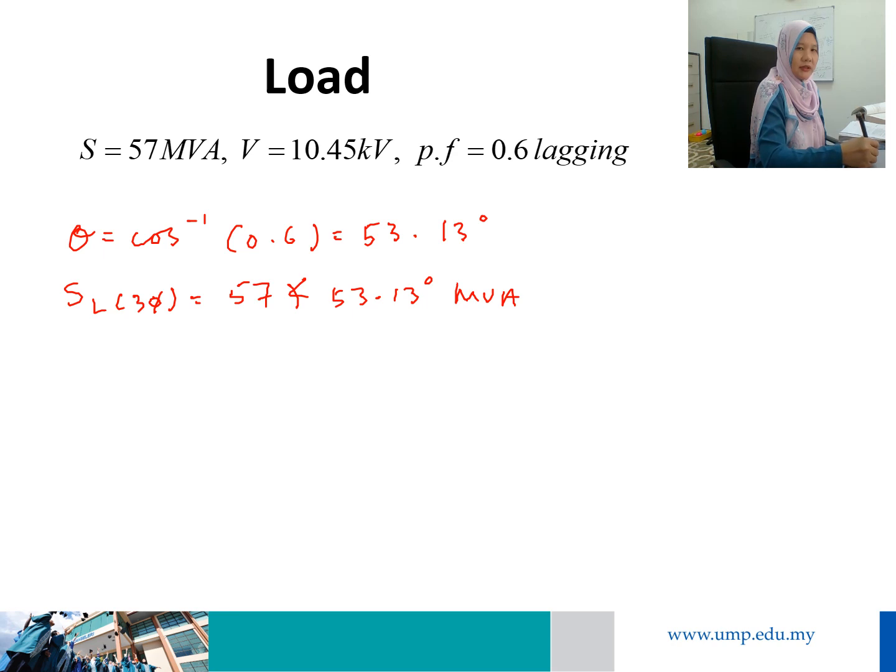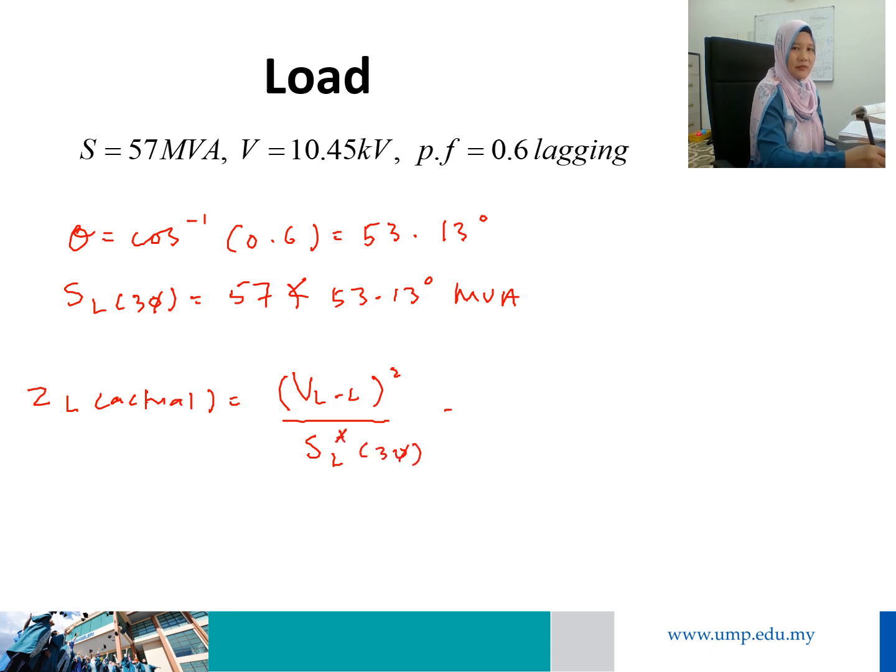And therefore the Z load actual is equal to V line to line squared divided by S load conjugate three-phase. Hopefully you have already learned this part in the circuit analysis too.